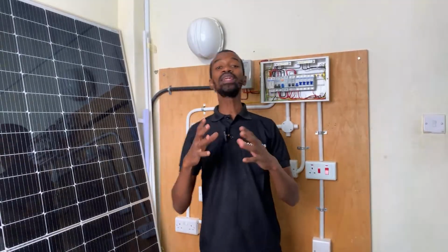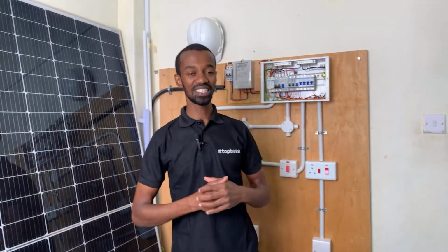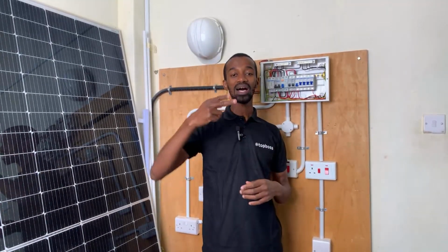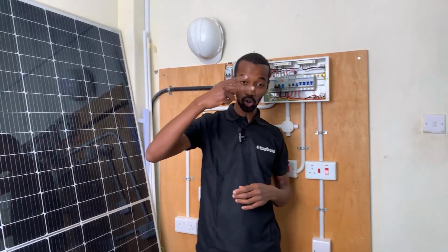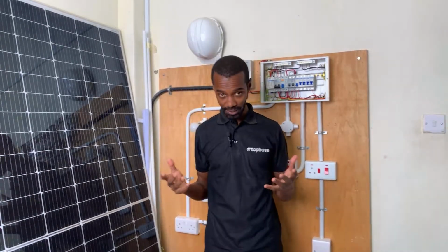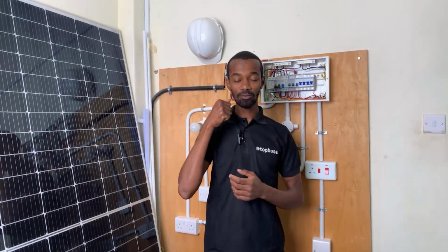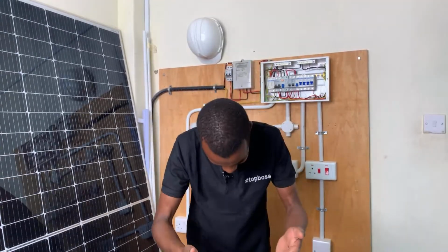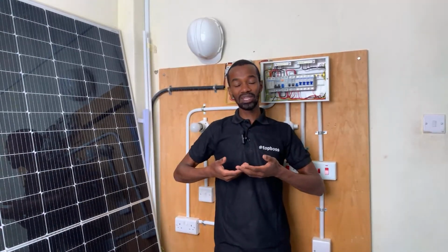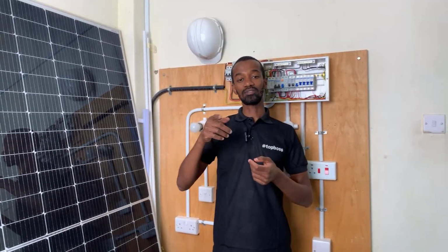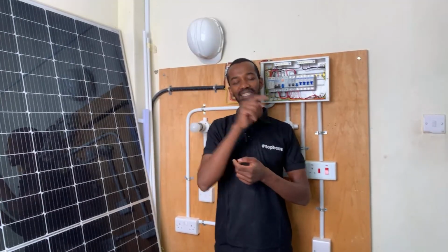Now, in a home or in a business distribution, you find that power is supplied with two conductors, the phase and the neutral. The phase is where current is flowing from the source, which is the transformer, and then it flows back through the neutral path to the transformer, completing that circuit.